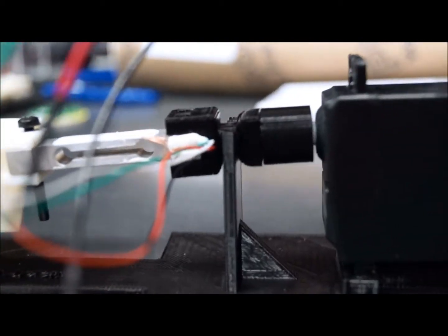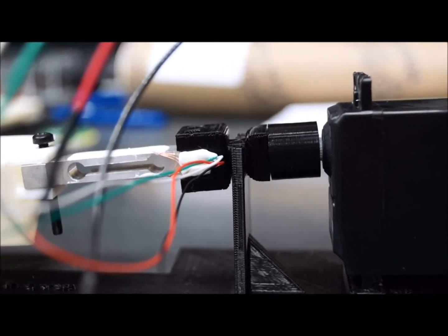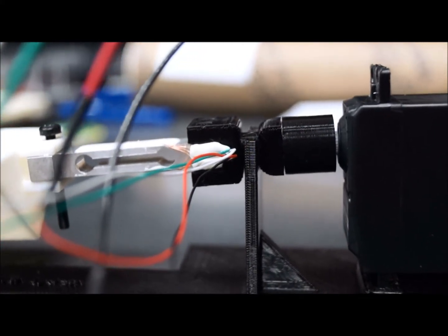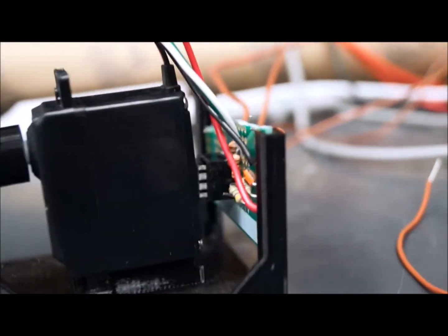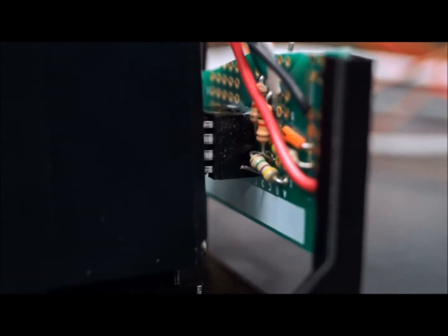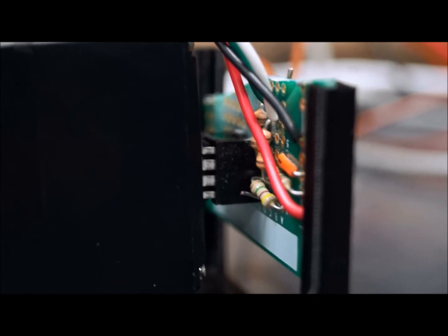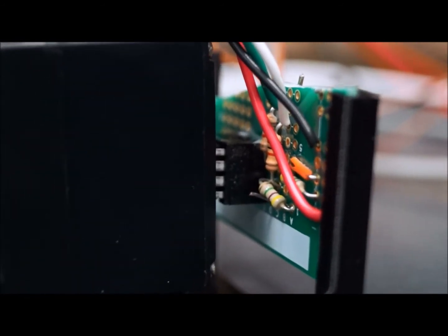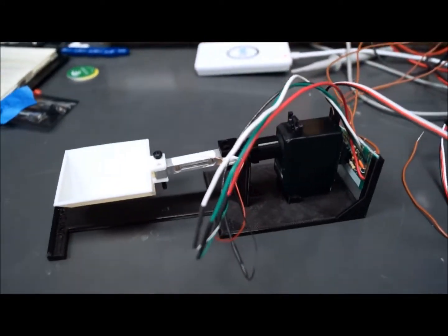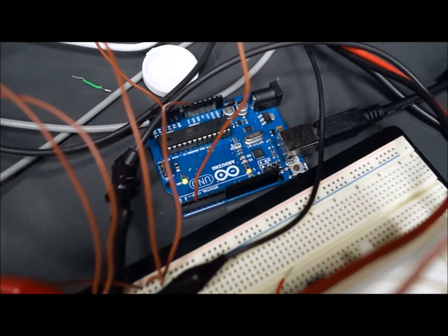Further along the line, we have the 3D printed adapters that will convert the rectangular shape of the load cell to a servo head. Here's the standard servo, and in the back is the logic for the whole system. The op amp that we're using is a standard MCP6002, and we are using a differential amplifier to amplify it about 4,700 times. This is all being controlled by an Arduino, which is then connected to this computer here.